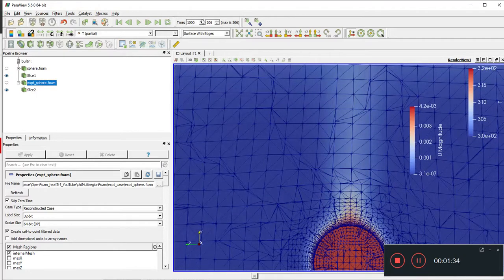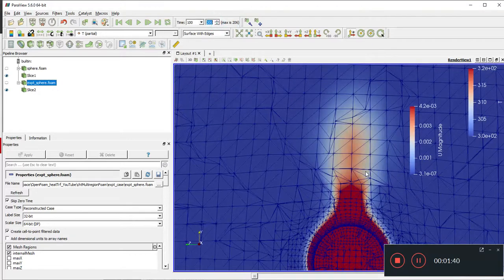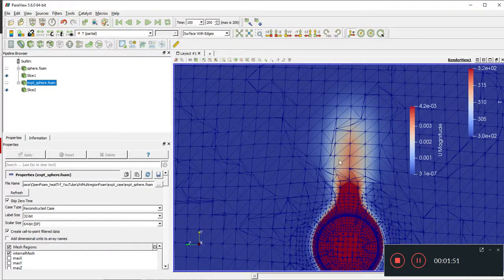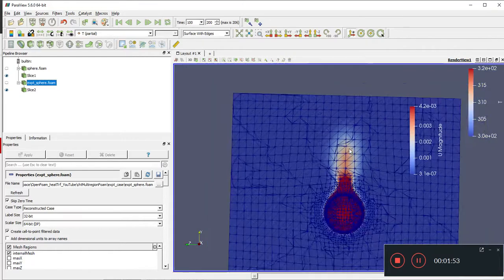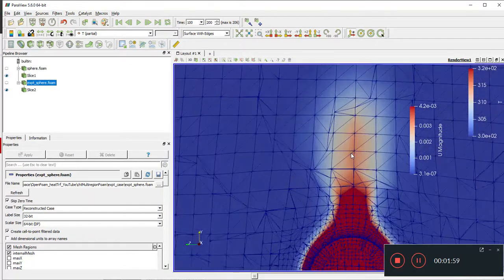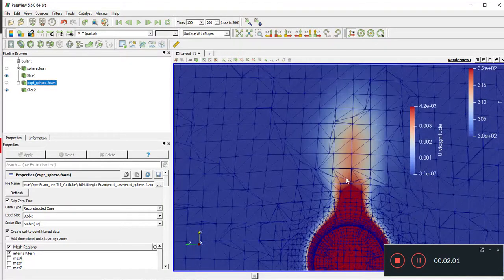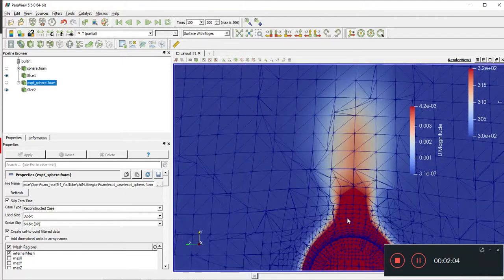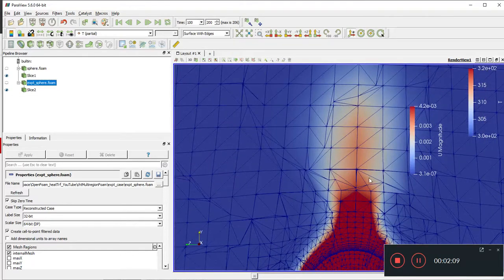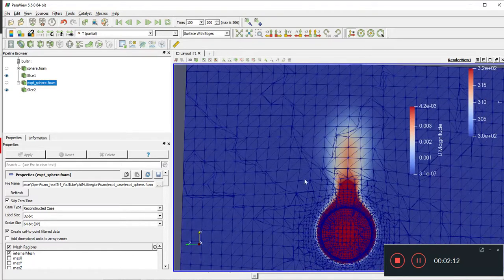You can see the temperatures. This is like the end bit already. At t equals 100 seconds, you can see that because of the mesh along the boundaries of the mesh, this phenomenon is actually happening, and that's not good. So probably what we want to do is have our whole mesh refinement over here in this area, preferably on the top.